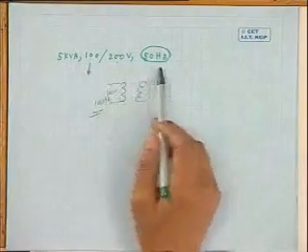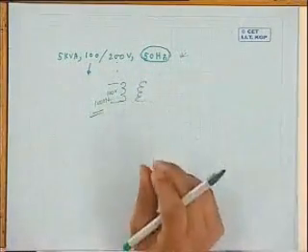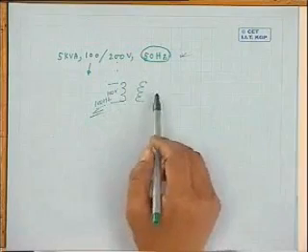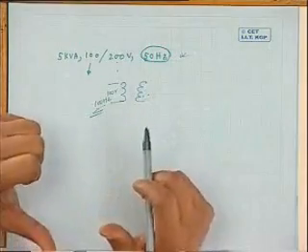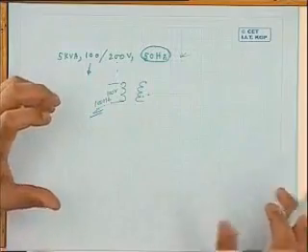Then you will perhaps load it like that. What I am trying to tell is, for a transformer designed for 50 hertz, you maintain the same RMS voltages on the respective sides but apply 100 hertz. You will get here 200 volt, 100 hertz. But in which way will the performance of the transformer be affected? Will it become better? Definitely not, because with this frequency your core loss may increase, because it depends on f squared, and with 100 hertz your flux density also decreases.